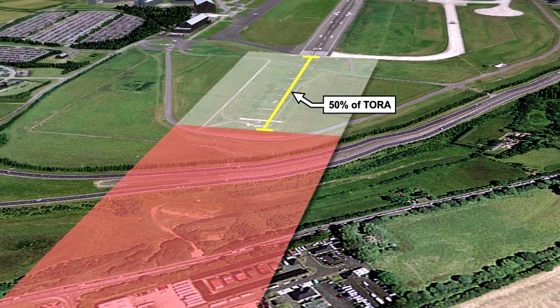If this is the case, a pilot must not use this extra amount in his performance calculations. To summarize, a clearway is designed to be an area free from objects which may cause hazard to an aeroplane in the initial phase of flight, particularly in emergency situations. The clearway serves no other purpose and therefore may not be used as an extension to the landing area or stopping area.